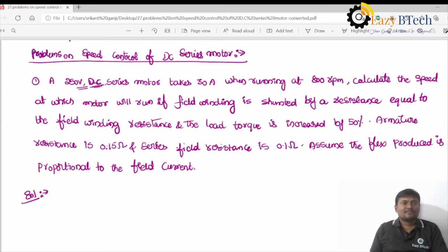In this lecture, I will solve some problems on speed control of DC series motor, the most repeated problems on speed control of DC series motor. A 250 volts DC series motor takes 30 amperes. It means the line current is 30 amperes.